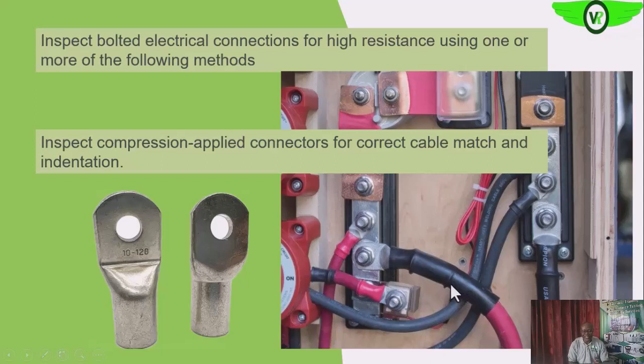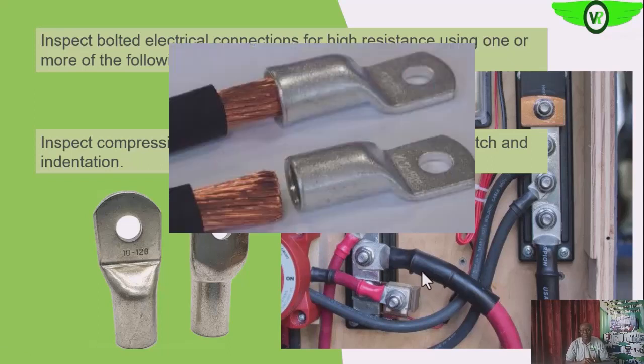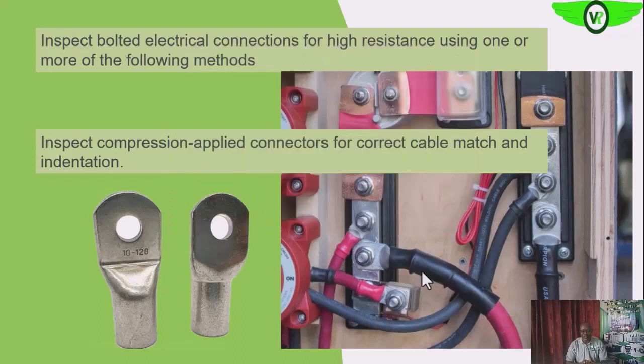Be sure that it is not oversized, because if it's oversized, the cable will be floating in the terminal lug, and if the cable is floating, that will give an avenue for loose connection that will eventually result in a high resistance point that will result eventually in hot spots, because the amount of heat that will be dissipated at that particular spot will definitely go up because of the looseness, and then that will become a potential point for failure on your installation.